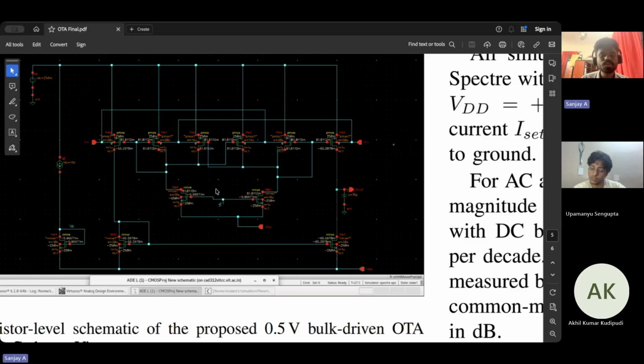How is M equal to 0.7 achieved by sizing? Since both M7, M8 and M2 share the same L, that is channel length, and the VGS, their transconductances scale with W, that is width. So M is equal to width of M7 divided by that of M2, which is 14 micrometer by 20 micrometer, exactly 0.7. That's not a coincidence. The sizing is directly derived from the target feedback coefficient.